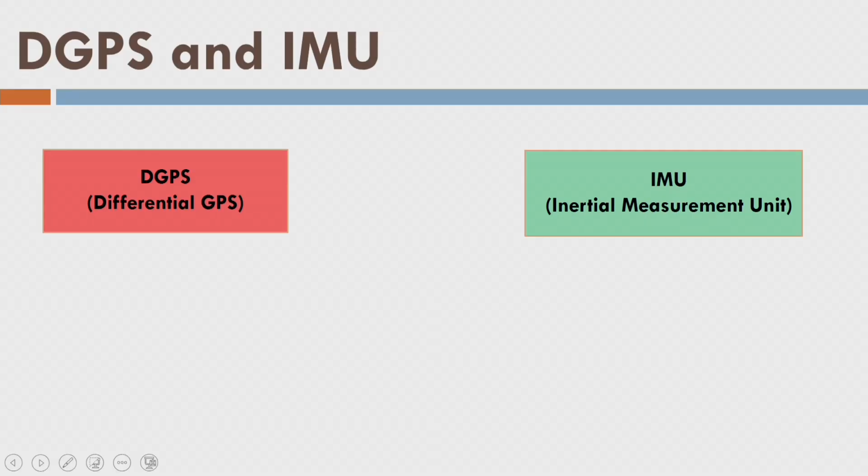So now let us understand the role of the DGPS and IMU. DGPS is the differential global positioning system, and you can imagine that the aircraft has a DGPS mounted over the top. It is in connection with all the satellites, and satellite lock is maintained, right? So what happens here? It is acquiring data every 1 second, the x, y, and z position of the aircraft trajectory, right?